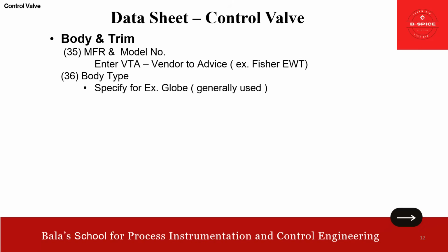Okay, friends, there are some other valves also. There are three-way valves, used for flow diversion or flow mixing. And ball valves also, which are generally used for on-off service. I think this information is very useful. Then we go with body and trim size.